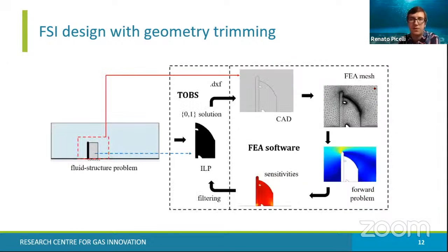That's why I'm saying we are decoupling analysis, the finite elements, and the optimization variables, the design variables. So we have a grid of points upon this mesh, and we extract the sensitivities at the points. I carried out finite differences, creating nodes right at those points, and it worked out. So at least at this point, I'm confident that I have something.